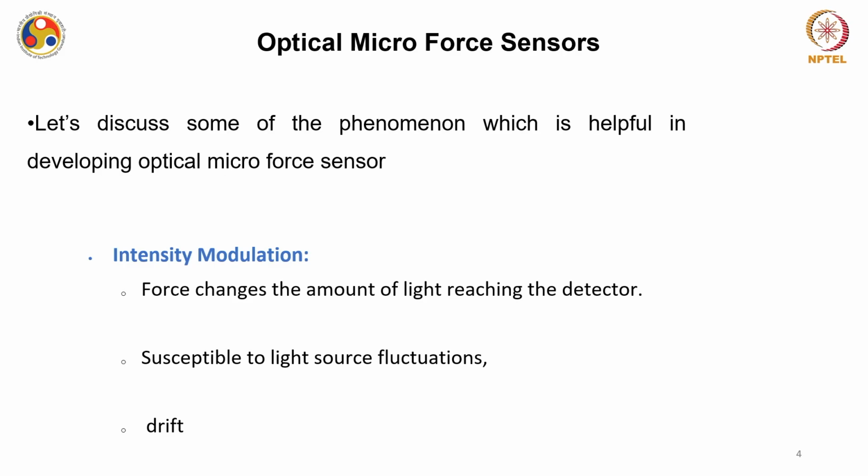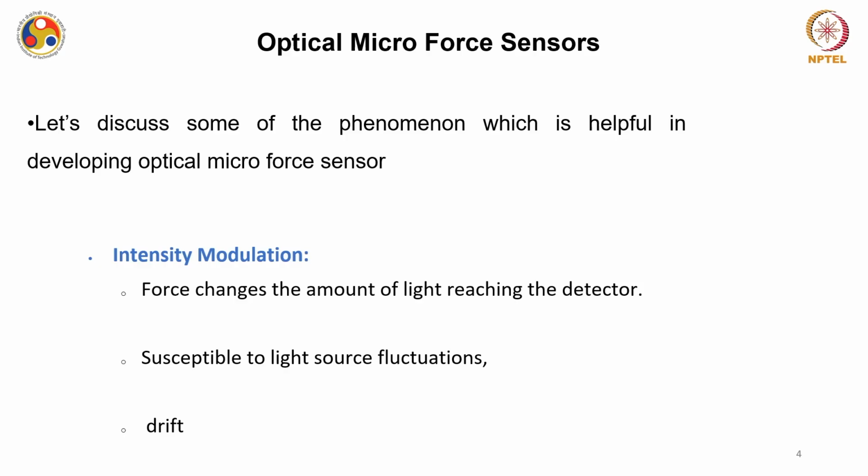All right. So, let us discuss some of the phenomena which are helpful in developing optical micro force sensors, and the first phenomenon that we are going to discuss is the intensity modulation, or the changes in the intensity that is detected by some photodetector or some other means. So, force changes the amount of light that reaches the detector. Let us take one example.